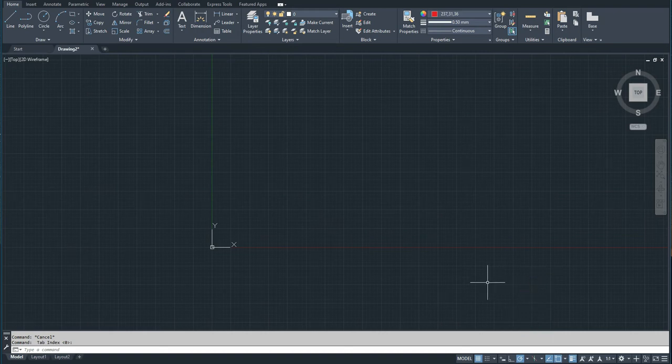What does that mean? That means if you select a line, as an example, select any point, see, it will give you 0. Plus 45. See, we have a green dashed line showing you that the polar tracking is on at 45 angle. And then 90. Then 135. 180. And 225. 270. And so on, guys. So it will always be incremented by 45.